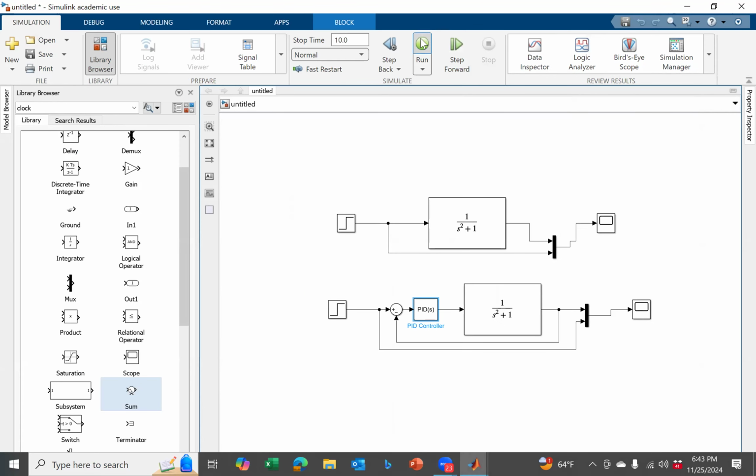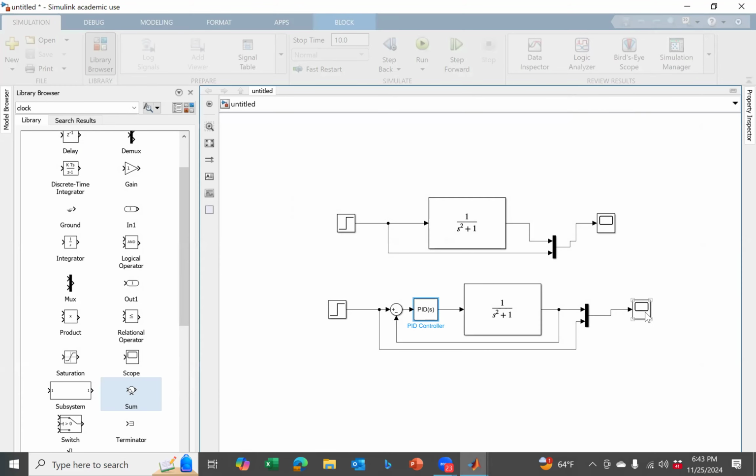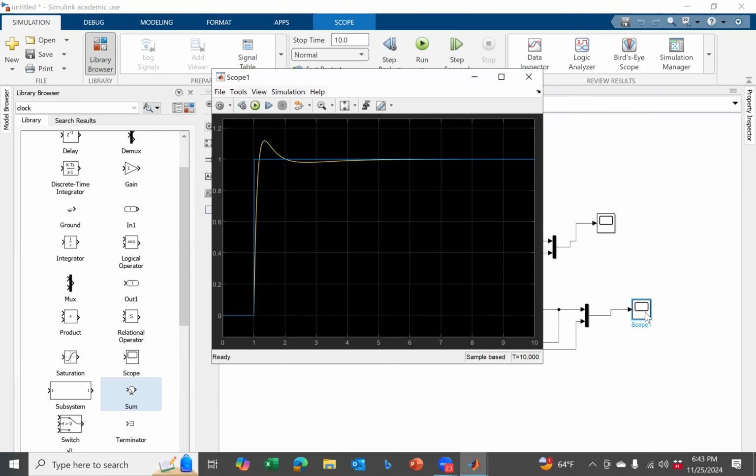Now, if I run this, I want you to observe that I have a system. Remember, there are no longer oscillations. My input is tracking quite well based on my specification. No oscillation, which means if I give a 60 degrees input, then my robot is not going to go haywire. There will be an overshoot, but finally it will go to 60 degrees. Everyone understood this?